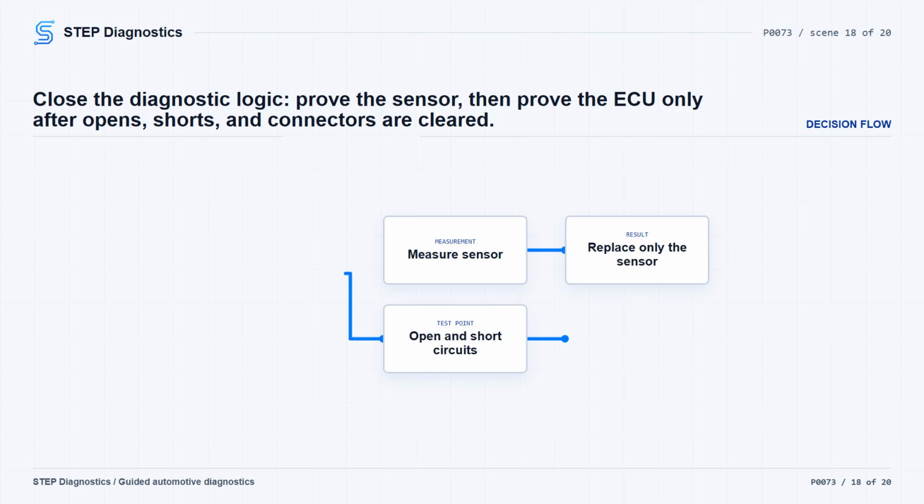If no temperature data is available, connect the test kit to the harness connector, switch to adjust, and slowly change resistance with the ignition on. The scan tool temperature or voltage should change as resistance changes. To verify an ECU failure, open and short the circuits and monitor both signal voltage and fault behavior. If the expected voltage changes or faults do not occur, and the circuits are not shorted or open, the ECU